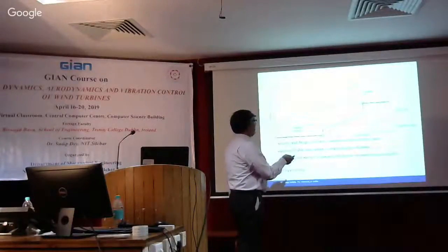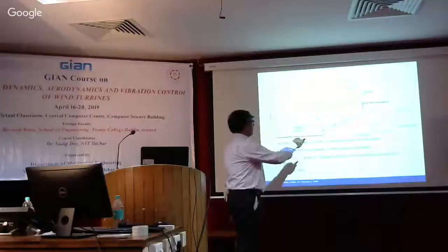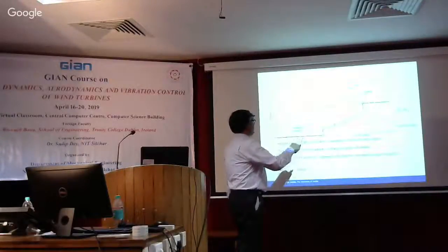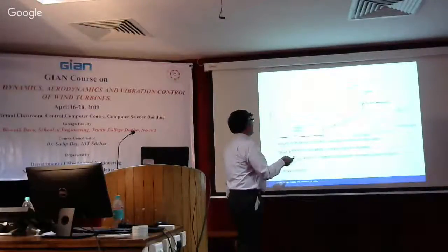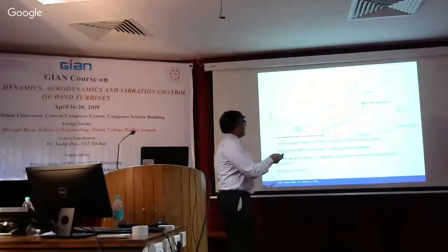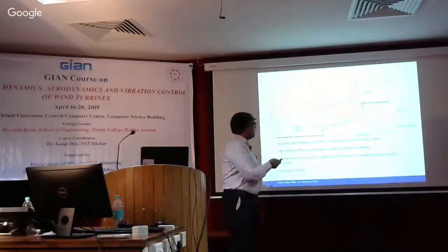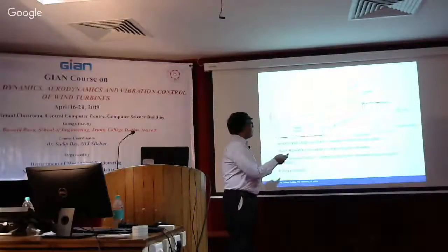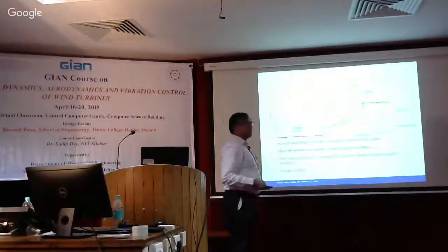When you're here, then we actually use the generated torque controller. Or for example, here, what we're doing is, again, making sure that when the speed is constant, your torque is of this particular value here. So you're fixing one and then changing the other to get the optimal value. So you're moving from here to here, or you can also move horizontally, where you keep your generator speed constant and then appropriately change the torque in this region.